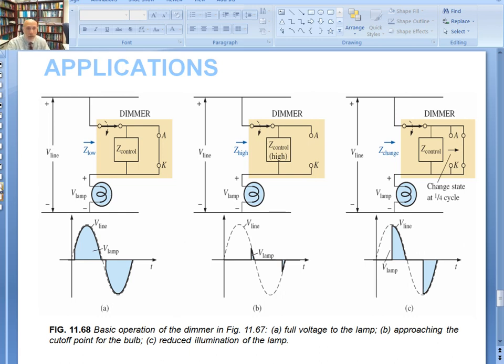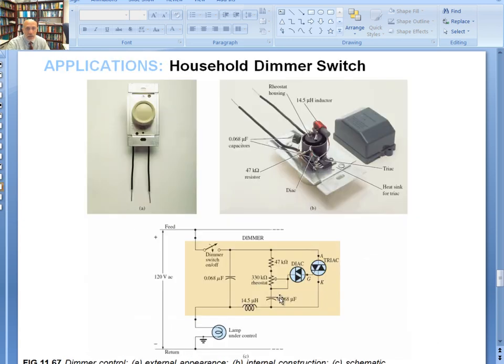If I look at the circuit diagram, here the control knob that controls the light intensity, in this case right here, is connected to a rheostat and a branch parallel to the triac. Now, the setting of the rheostat determines when the voltage across the capacitor reaches a sufficiently high level to turn the diac on.